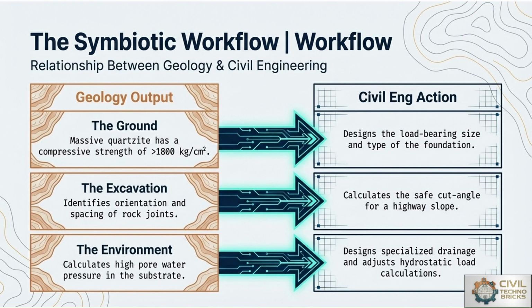The relationship between geology and civil engineering is a symbiotic workflow, which shows the relationship of geology output with reference to civil engineering action. Three phases are based on the ground condition, the excavation position, and the environmental condition. The ground condition, where massive quartzite has a compressive strength of greater than 1800 kg per centimeter square. That type of ground is most important in civil engineering action to design the load bearing size and selection of the type of foundation.